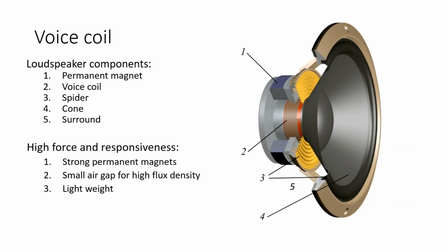But let's discuss briefly the overall modeling complexity of this system. On the input side, you would have some power supply and some amplifier which would supply the current to the voice coil, and then in the voice coil, this electrical energy would generate some magnetic field, which will in turn interact with the field of the permanent magnets and develop mechanical force.